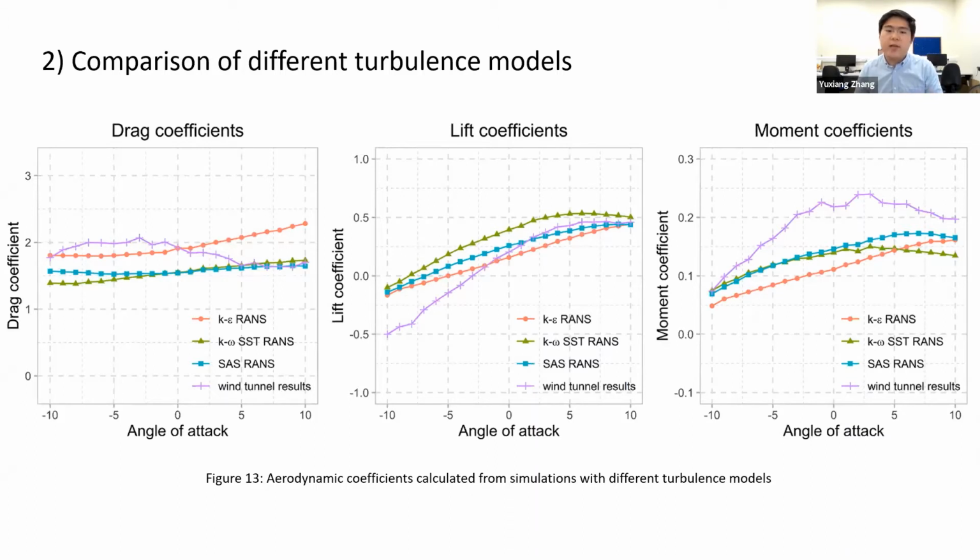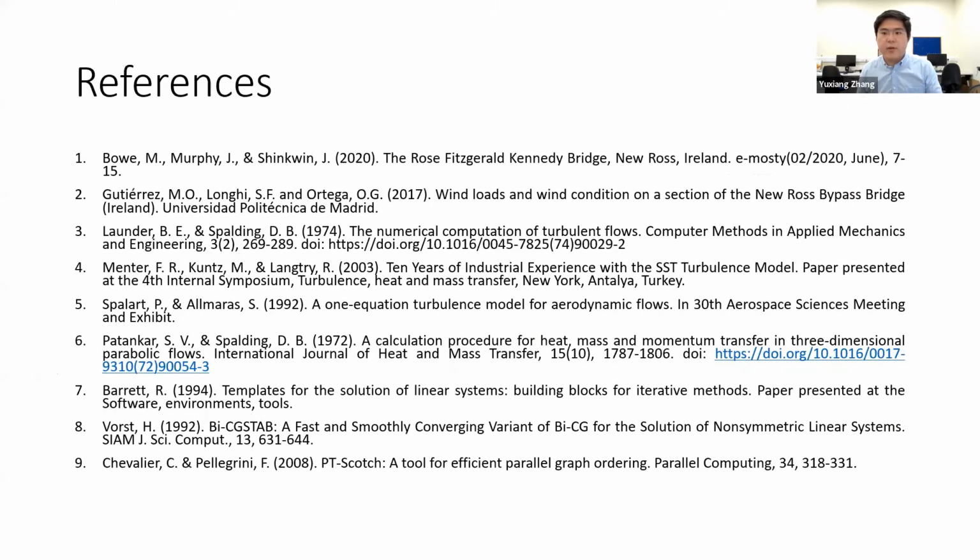We did not include the side plate geometries in the presented simulations, but an ongoing study is evaluating the side plate effects. Another finding is that aerodynamic coefficients derived from simulations based on the standard K-epsilon model show an almost linear correlation with the angle of attack. Such correlations are not seen in the other 3 sets of data. That's pretty much everything in my presentation.